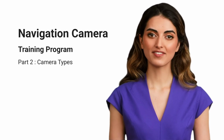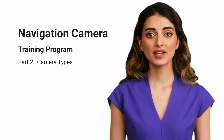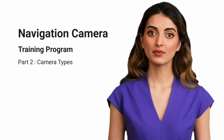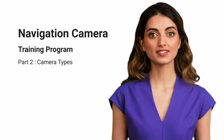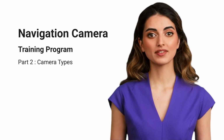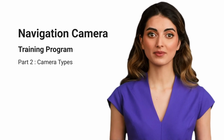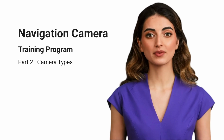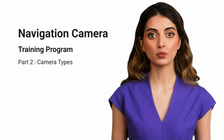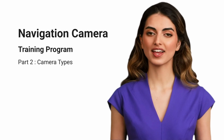Welcome to part 2 of our navigation camera series, camera types. In the previous video, we explored the key specifications that define camera performance, including resolution, field of view, focal length, sensor size, and pixel size. Now we will look at the different types of cameras used in unmanned ground vehicles, including day cameras, low-light cameras, infrared cameras, thermal cameras, and perception cameras. We will understand how each camera works, where it is used, and how multiple camera types combine to support navigation, observation, and autonomy.